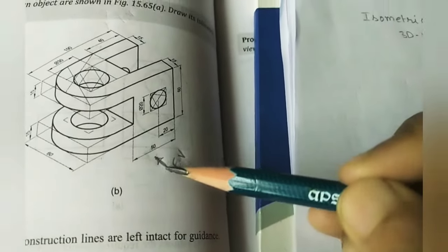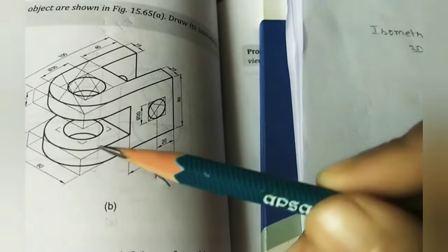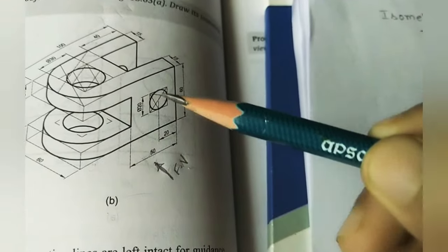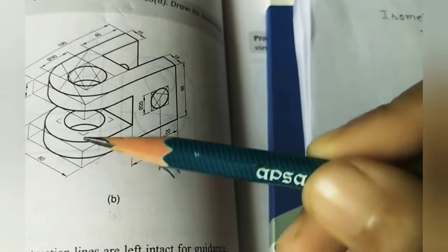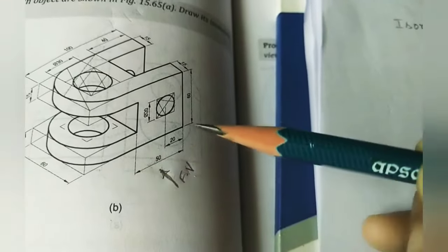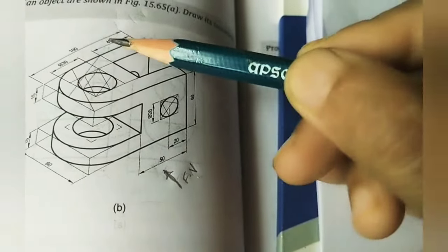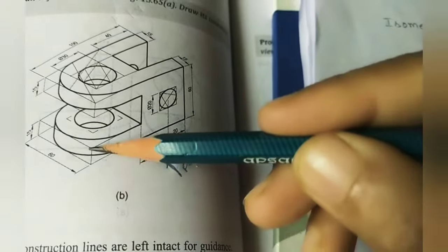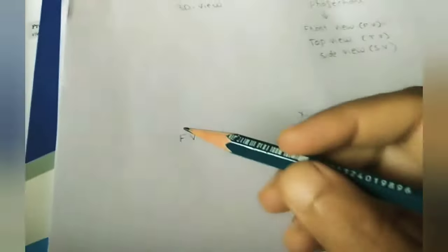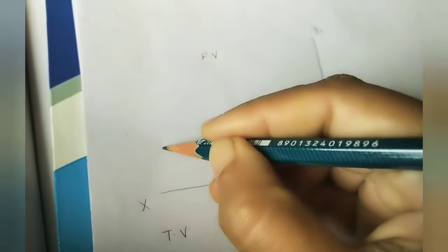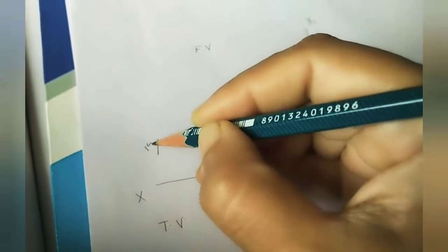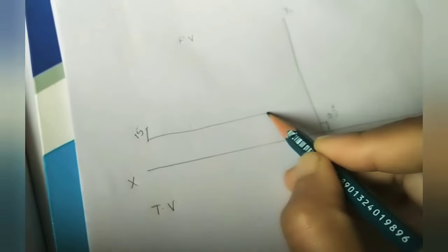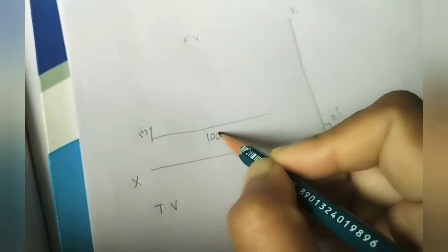If you see the object from this direction, we can see this U shape, correct? How much thickness is it? 15 mm, one line, and then the entire width is 100 mm this side. 15, 100. Let us do this L initially. In this portion I am drawing, this is 15 mm, roughly, and this side is 100 mm.